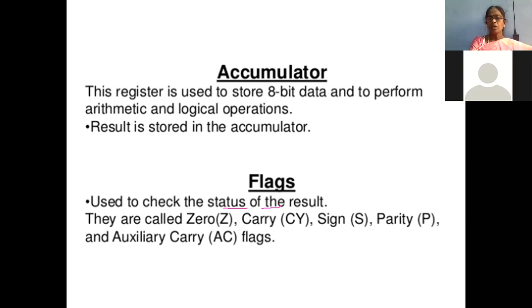Yes, right. So there is a difference with the carry flag. After adding two 8-bit numbers, if there is excess data, we say it is a carry. But in the case of the auxiliary carry, when you are adding 4 bits internally and a carry is generated, that is reflected in the auxiliary carry flag.